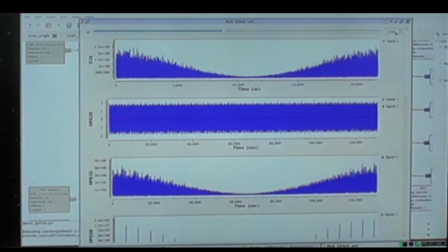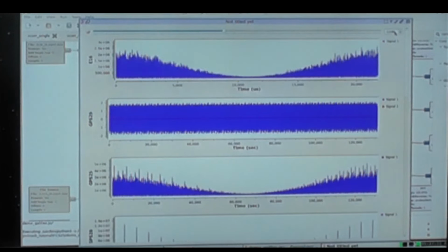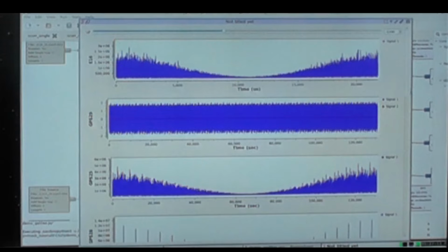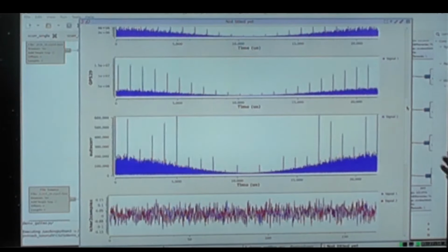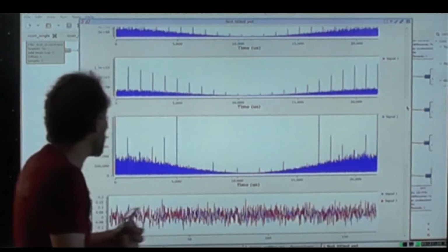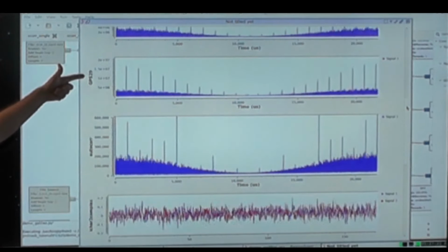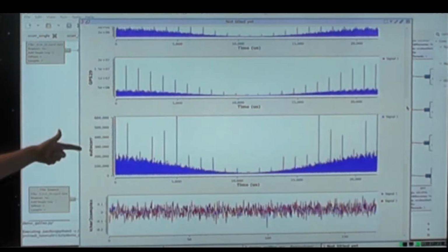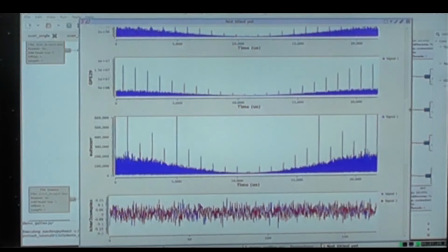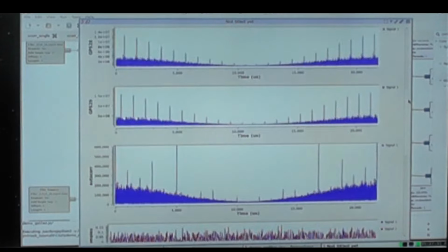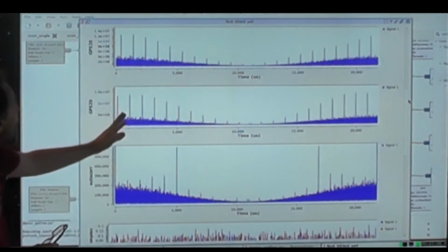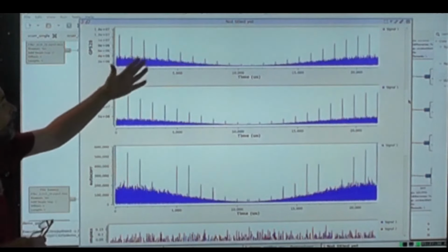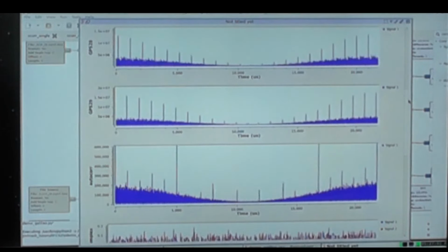So you see in this example, I put a frequency offset of 1.1 kilohertz, and it happens that in this recording, there are two satellites that exhibit a Doppler shift of 1.1 kilohertz, GPS number 29 and the one above, 29 and 25, I remember well, 29 and 28, sorry. So 29 and 28 both exhibit correlation peaks when you frequency offset by 1.1 kilohertz.